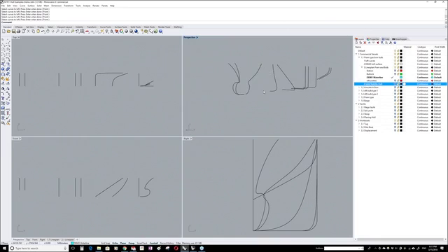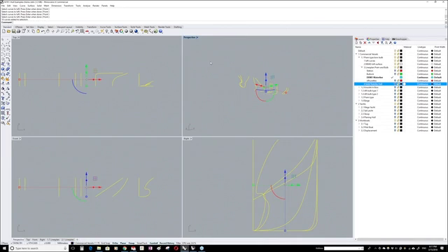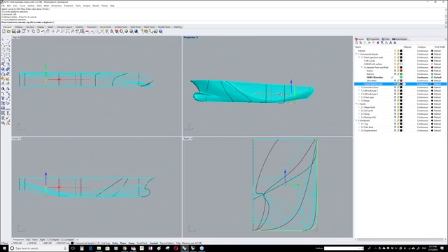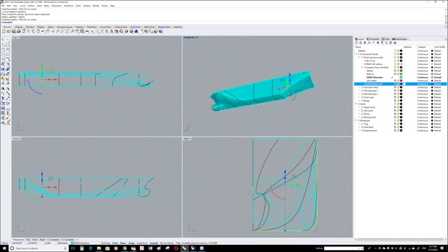You shouldn't do that, especially when you use record history and if you select everything together. Rhino has an algorithm behind it that automatically lofts nicely and without twisting. Something you should avoid with loose loft is, for example, when you use record history and then move one of the curves out of another one. You see it becomes very ugly, and you get a very bad shape as well, and a bad mathematical product within Rhino of the NURBS surface. So don't do this.